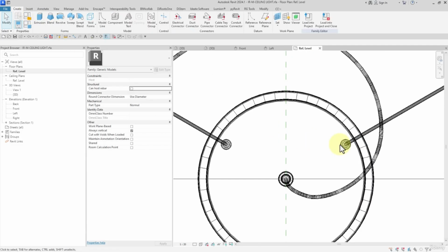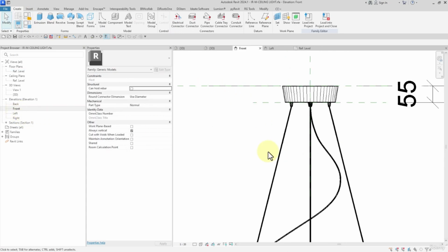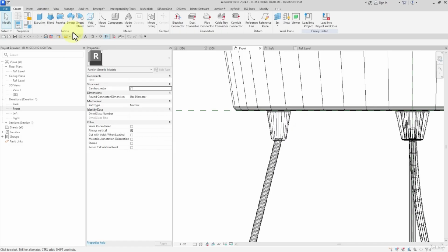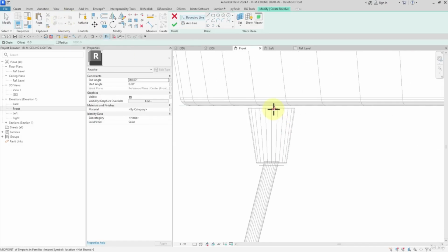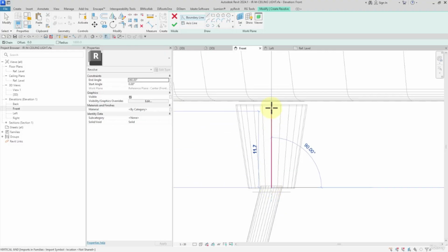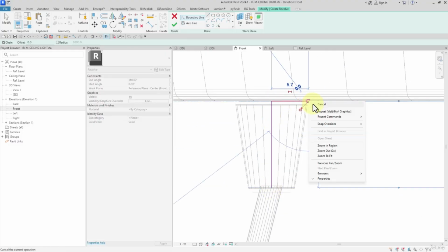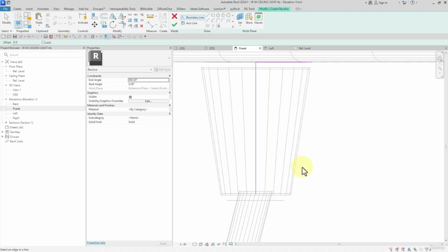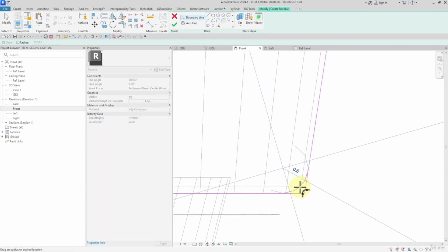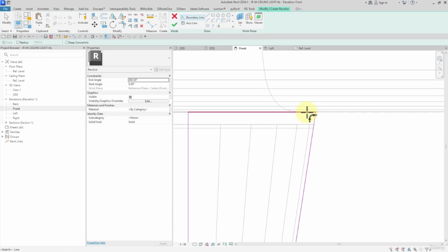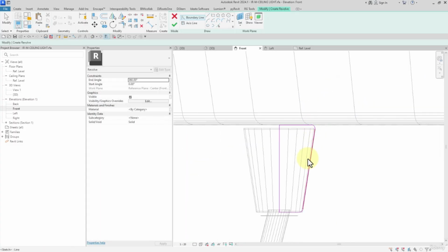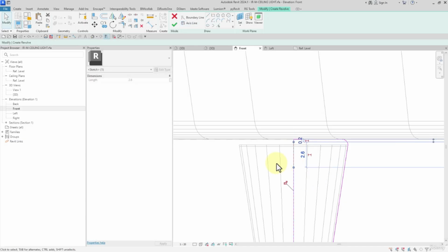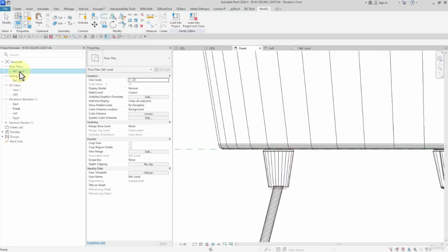We can use the tool of Revolve for modeling these. As you can see, Revolve is very functional. Again, I select Revolve, then I click at the center. Watch this. Since I want to connect it to the body, again one line, trim, like this way, and then using fillet, I add a fillet at the corner, like this way. Watch this. Axis line right here, and finish.